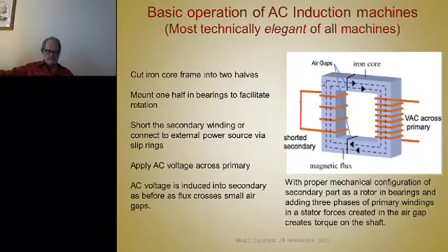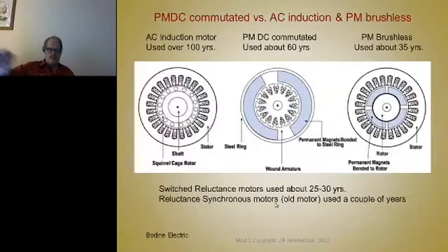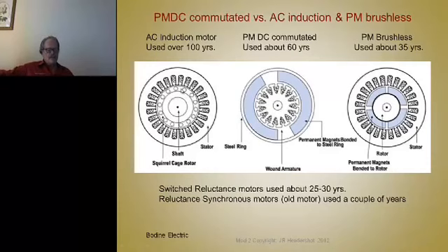But anyway, if we were to somehow put a shaft in here and put an axis of rotation there and allow this thing to rotate around there, and add some more coils and some more poles, we would turn that into a machine that looks like this. So there's our stator with the windings in the stator, 3 phases, and there's our rotor with the bars that form that shorted turn. And this is a 2-pole motor. Half of these bars, the current's coming out of the screen, and the other half of the bars, the current's going into the screen. And so it's just one shorted turn there with a bunch of conductors as a parallel path.